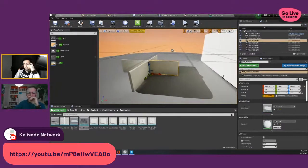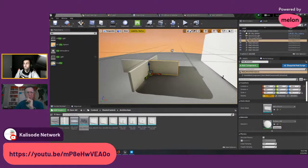So this is called the static lighting, the baked lighting. This is really performant, and this is what most of the architecture visualization projects use. If you have a really great GPU, specifically an RTX card, like the 20 series of NVIDIA and 30 series of NVIDIA, you have the option to use GPU Lightmass instead of CPU because, as I told you, this whole process is CPU based. So you can make it a GPU based process.